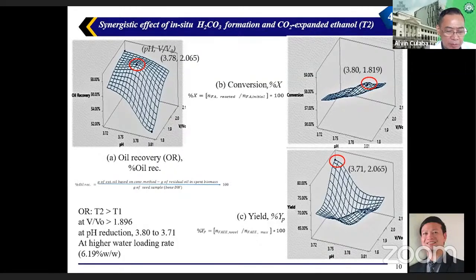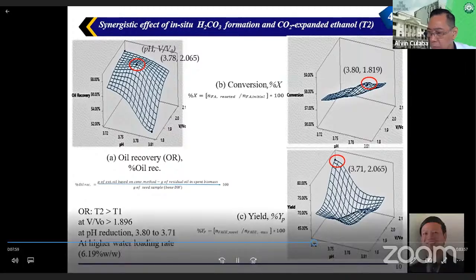The decrease of the conversion by 3% and of the yield, despite the increase of the oil recovery and the increased volume expansion, could be attributed to some phenomenal effects during phase equilibrium, chemical equilibrium, or kinetics, either individually or collectively. The increased amount of water in the feed dilutes the concentration of reactant so that kinetic effects can occur.